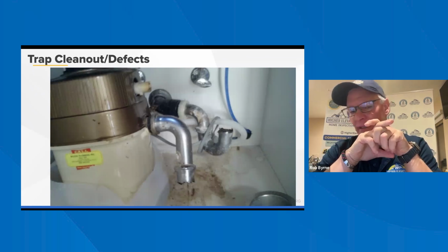If you folks are doing inspections out there, a lot of times you'll see that corrugated drain. That's basically a temporary drain that a plumber would never do. That's like a DIY, where they need to change this and they're not going to start cutting and making it perfect, so they take that and use it. What I do is I run the water and take my flashlight and shine it behind there, and I show the clients how all of that debris gets built up in that corrugated section, and you can clearly see the water flowing.